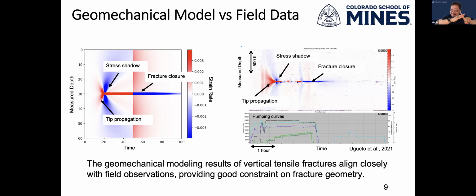Nothing weird. But there's one thing that is very abnormal. It's because in the normal case, right, if I'm fracking a wellbore like 200 feet in here, because fractures are all parallel to each other. Let me go back to this plot. If I'm fracking a wellbore, let's say this blue stage for 200 feet, I'm expecting the range of the fracture hits at the monitor well should be around 200 feet.